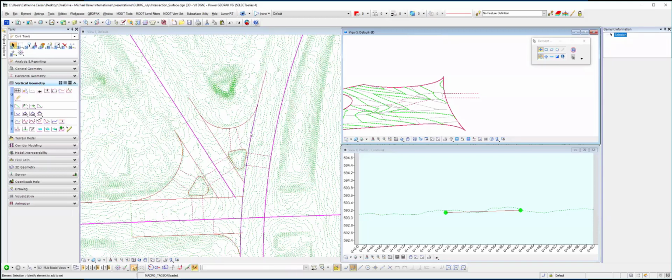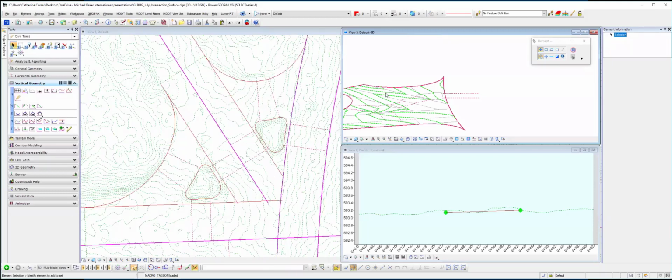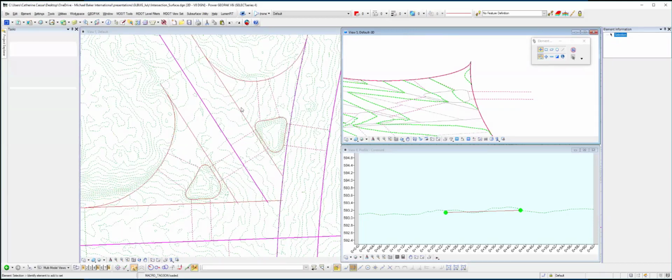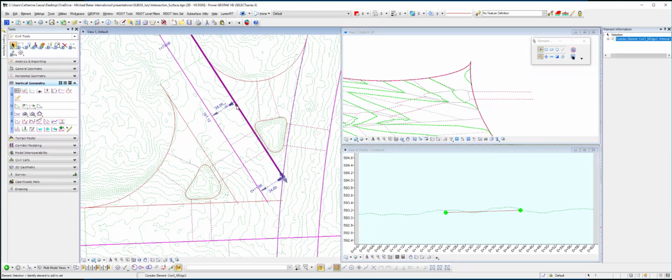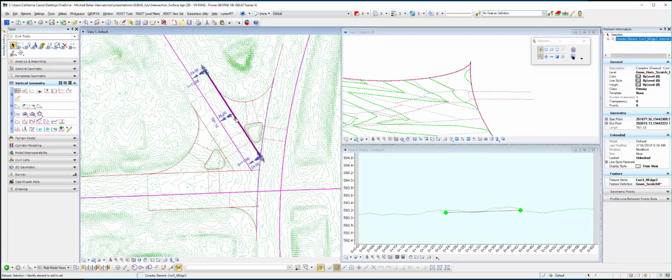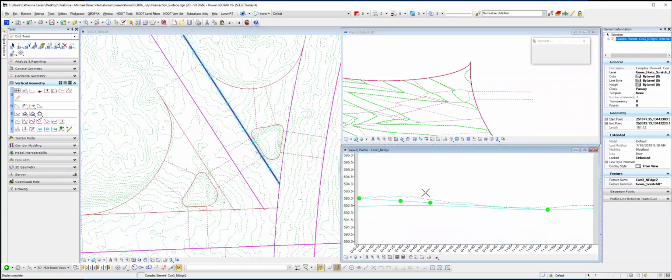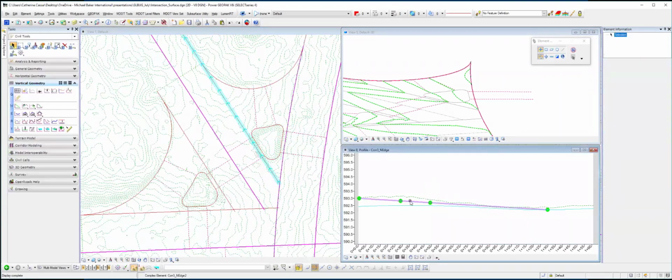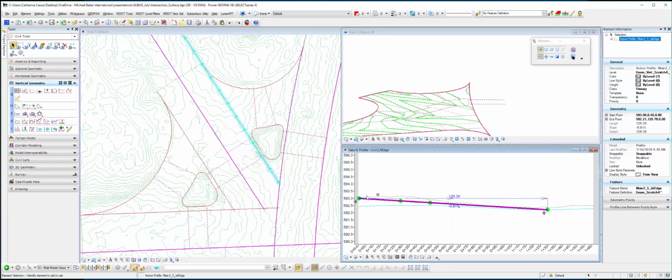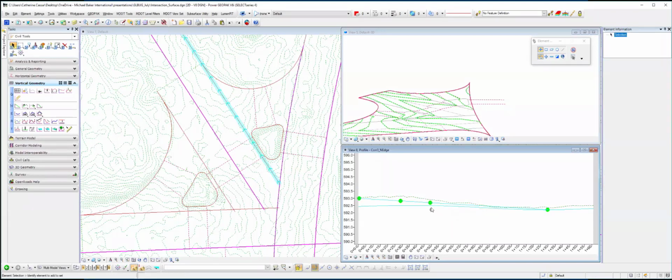So in a final surface model, in this case, we've manipulated these edges. And in here, this line, you'll notice, goes beyond the limits of what my model would be. However, its elevation information is only coming from the points where the vertical profile is. So this was the projected profile based off of this vertical alignment. These are what it ends up being when you create the profile to make sure you're tying into everything.